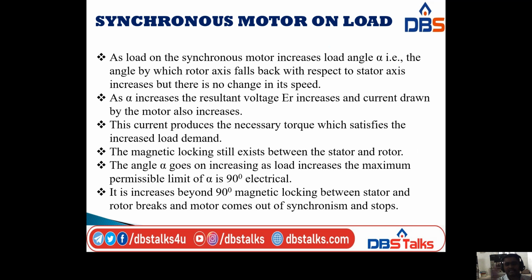Next, coming to the second case, that is the synchronous motor on load. Previously we discussed the synchronous motor off load, that means no load conditions, and now we are going to the synchronous motor on load condition. As the load of the synchronous motor increases, there is no change in the speed, but only a change in the load angle alpha. Why? Because the angle by which the rotor axis falls back with respect to the stator axis increases, but there is no change in its speed.